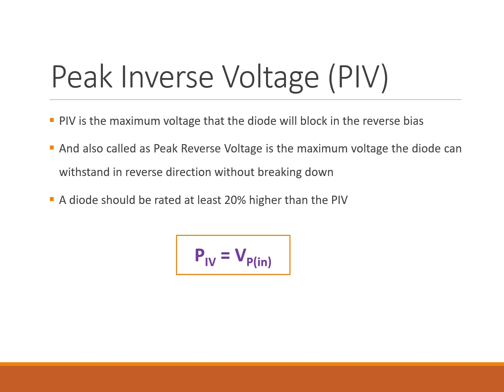If the diode isn't rated high enough for the circuit that it will be working in, when it goes into reverse voltage, it's basically going to punch through the component, through the material, and it's physically going to destroy the component. So the diode starts breaking down, it goes into overvoltage, and it just fries.